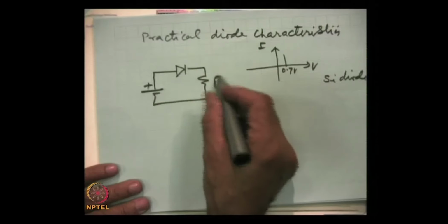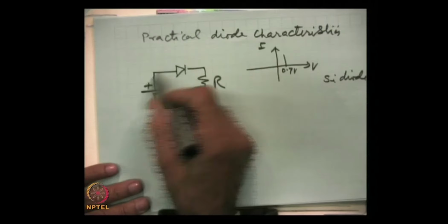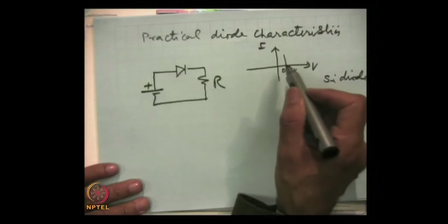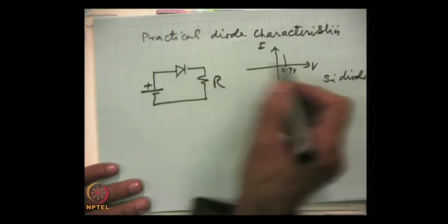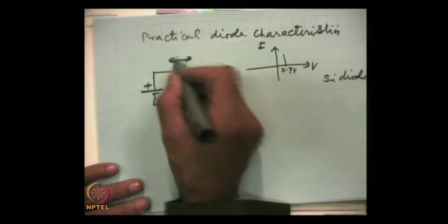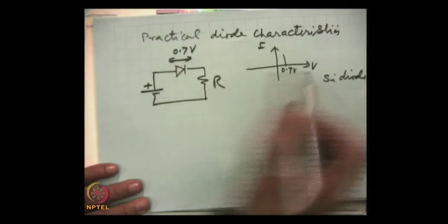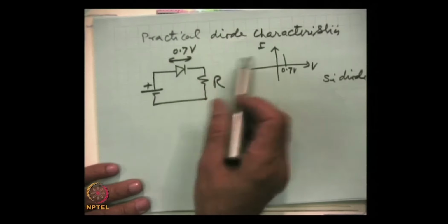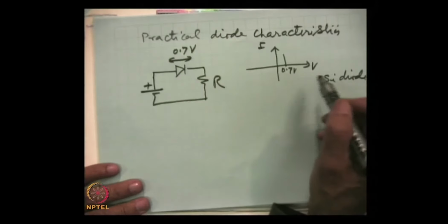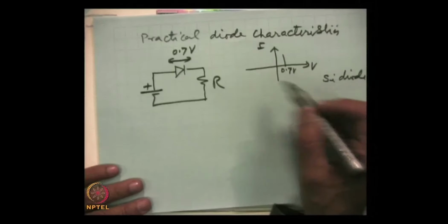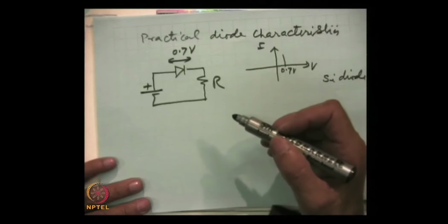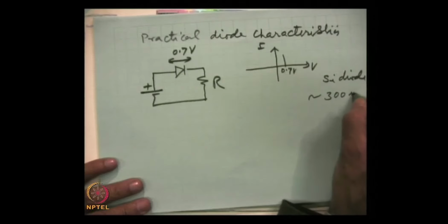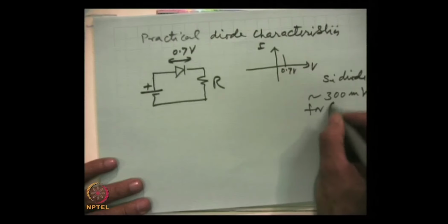this is the forward bias diode, and when this voltage is above 0.7 or close to 0.7, then the drop across this, that is the meaning. When the diode is in on state, practically we take, if it is a silicon diode, 0.7 volts drop, that means 700 millivolts for silicon diode, and this is around 300 millivolts for germanium diode.